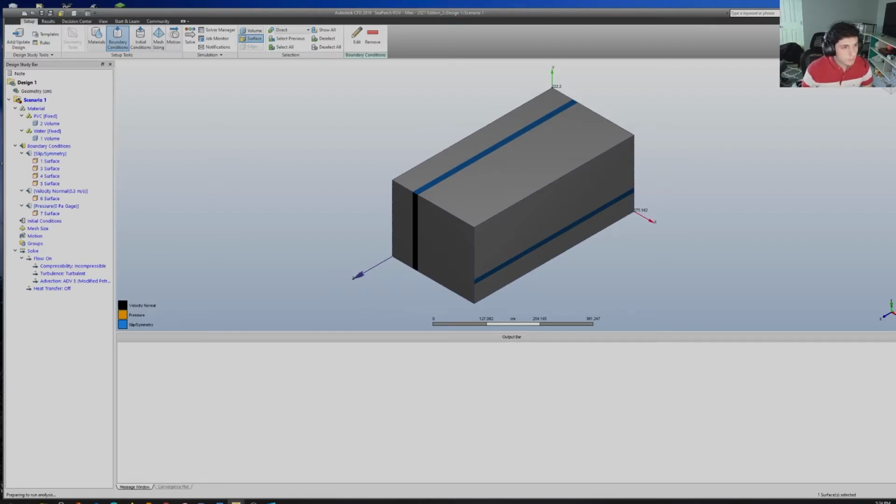That said, you can increase the efficiency of the propellers depending on how you streamline the flow around your bot into where the propeller intakes water. That can be accomplished by understanding fluid dynamics and optimizing the flow of water so it's more streamlined, and maybe even ducted into your propellers.